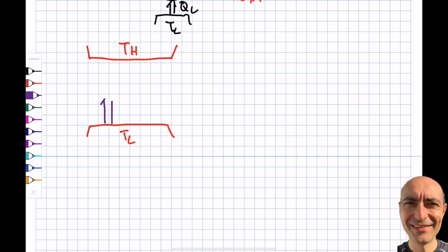Let's say that this is my refrigeration cycle, and let's again say that this is QL. Let's say that there's no work input, okay, which is not good according to the Clausius statement. I had to plug this into an outlet, right? But let's pretend that is the case. And if I do an energy balance over here, if there's no inlet, there's no exit, this needs to be QL too. Whatever comes in must come out because this is a cycle at the end of the day, right? So this will be QL from the first law, okay?